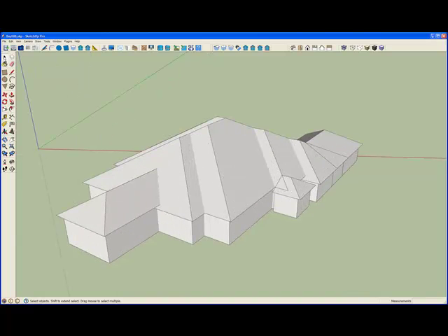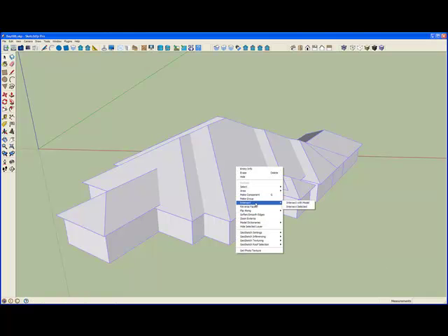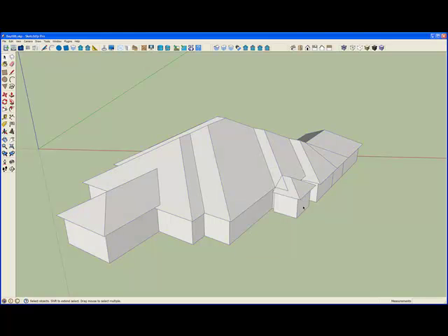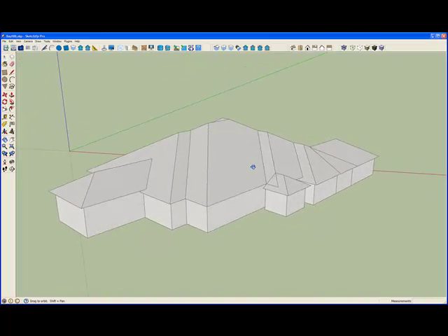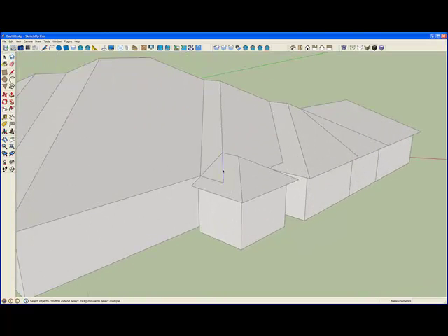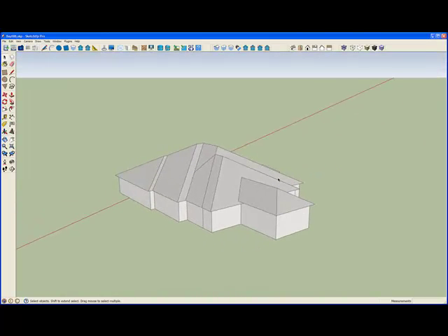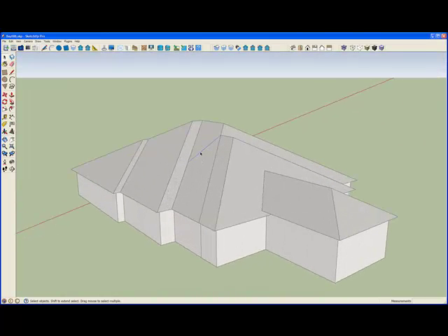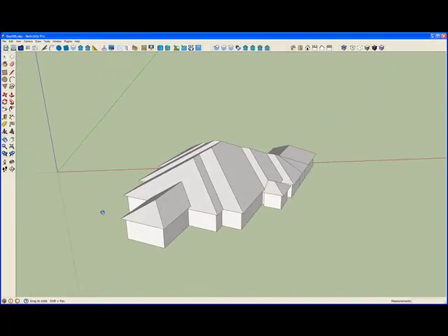And then at this point we will select all of that geometry and use the intersection tool to intersect it with itself. So we intersect selected, and it creates all those edges. We get some redundant edges which we can delete. Those faces are actually coplanar. So if we select this edge and delete it, and this edge and delete it, oops, this edge and delete it, and we can look around to the other side. And there are some extra edges as a result of that intersection, but because the faces adjacent to them are actually coplanar, deleting those edges is okay to do.